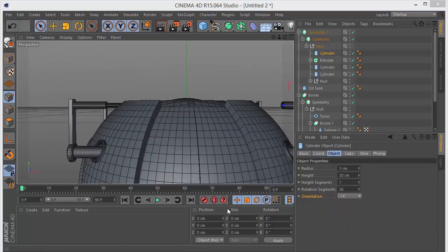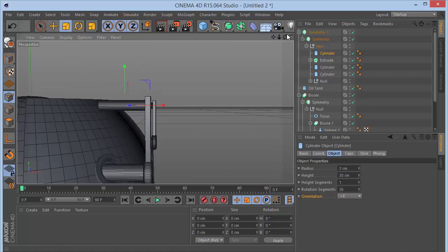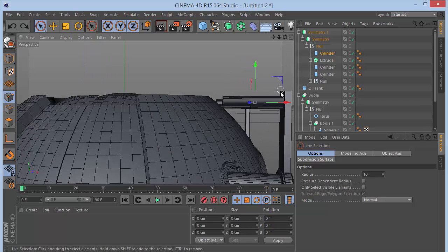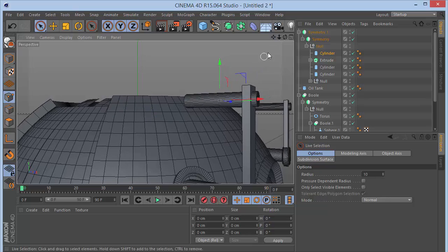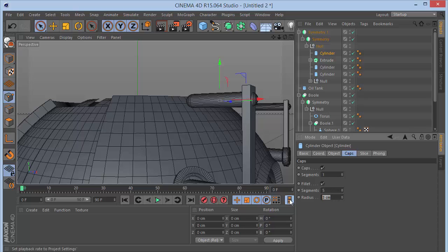I think I'll actually select this cylinder and move this out so that it is popping out a bit. Okay, like that, and give it some fillet, say 0.4 or something. We can give it a fillet of 1. Now that's too much. 0.5. I think that would do the trick. 0.5. Okay, push this in, and then we want to go into our front view.